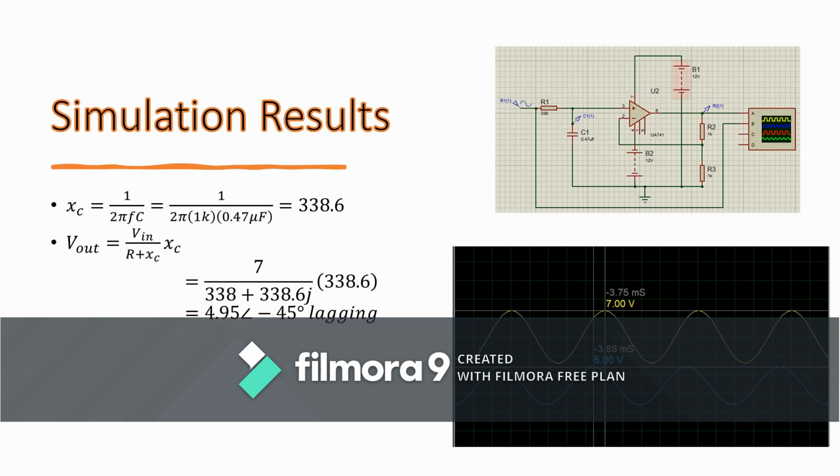In this circuit, I fix the capacitor at 0.47 microfarad, and after doing the calculation, I found that the resistor I need is 338 ohm. Then for the DC gain of this circuit, I will just set it to 2, because this is the minimum and the easier gain value to calculate. So I will set the R2 and R1 resistors to 1 kilo ohm.